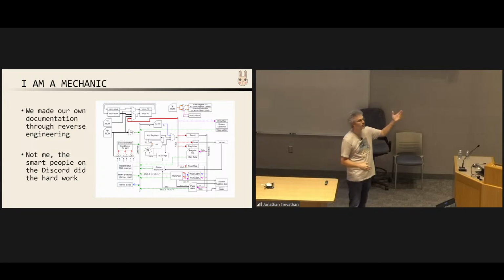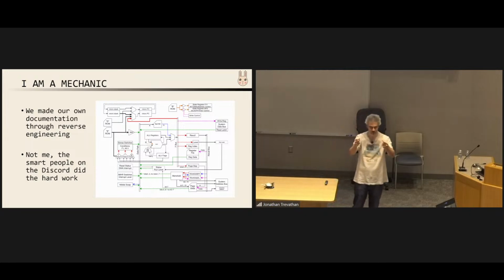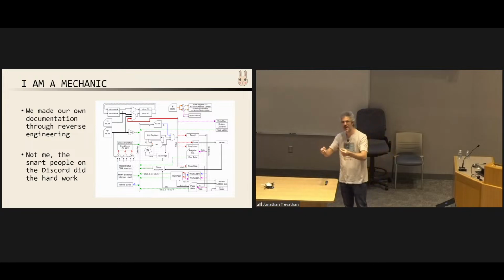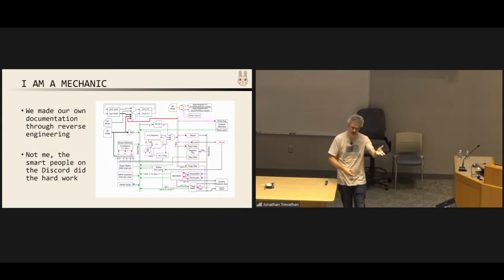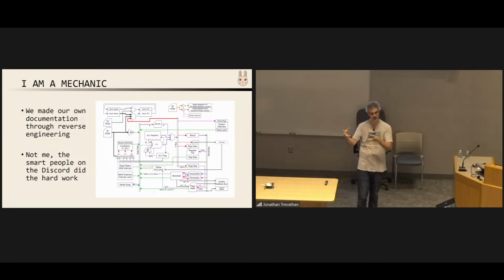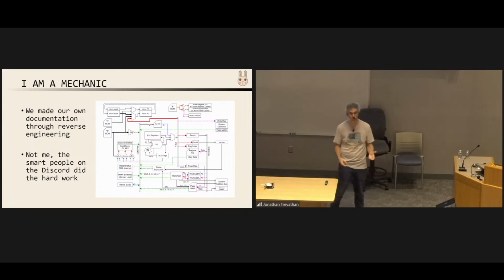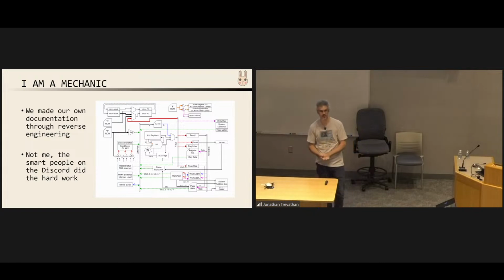And then me and about 3 other people over the course of 2 months sat down with a multimeter and a Zoom meeting and beeped out every single connection from every single IC to every single other IC. And since we could read what the ICs were, this is an AM2901, this is a 74LS04, this is an LS06 or whatever, we knew then how the logic all connected to each other, which means that we could then create something like this, which is a block diagram of how the CPU on a Centurion operates.